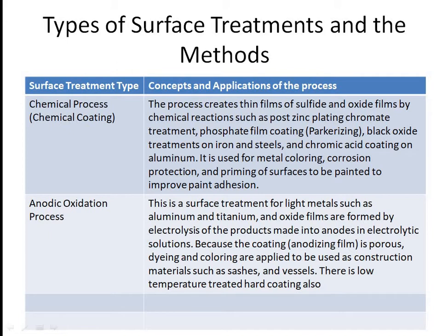So what it does, it removes the electrons from the substance and oxidizes the anode. So anodic oxidation increases corrosion resistance and wear resistance and provides better adhesion for paint primers and glues than does bare metal.